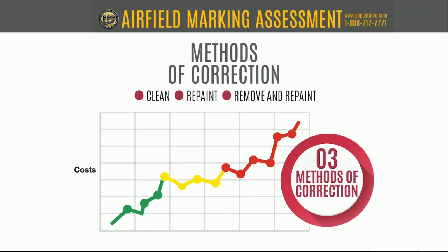So I just wanted to quickly digress. One of the things that we didn't mention with the new standard for minimum levels of reflectivity was a footnote in essentially FAA's standard for remarking when you're less than 100 millicandelas on white, 75 on yellow, 10 on red. They have a little footnote that says, prior to remarking, determine if removal of contaminants on the markings will restore retroreflectance.